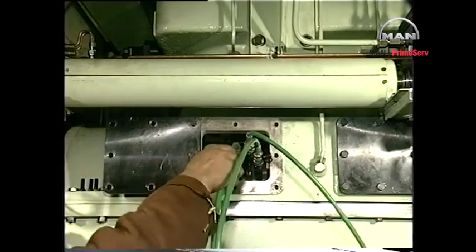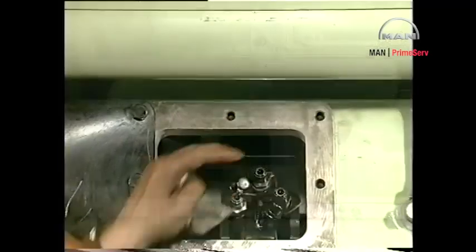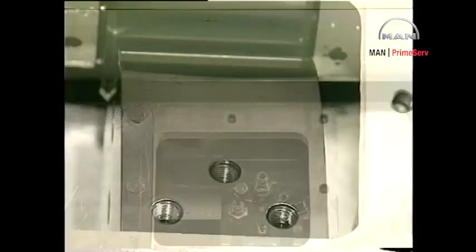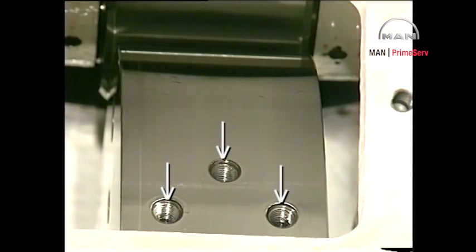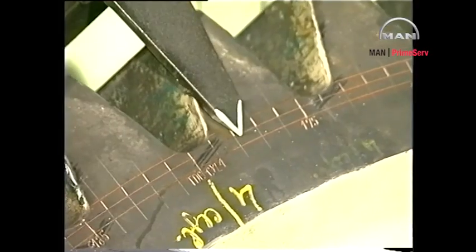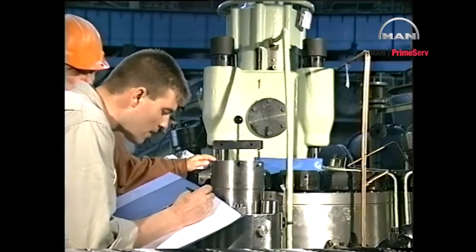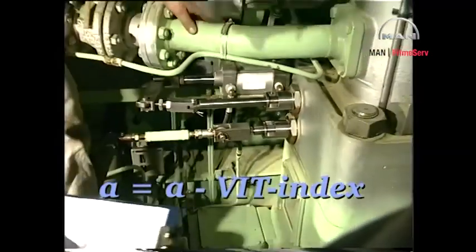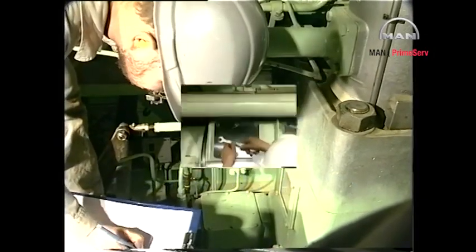Relieve the system of pressure and remove the spanner and hydraulic tools. Leave the cams to settle for a minimum of 15 minutes and then mount the plugs. Turn the cylinder concerned to top dead center and read the new fuel pump lead. Read the VIT index. If the VIT index is not at 0, the lead must be corrected before it is recorded in the engine logbook.